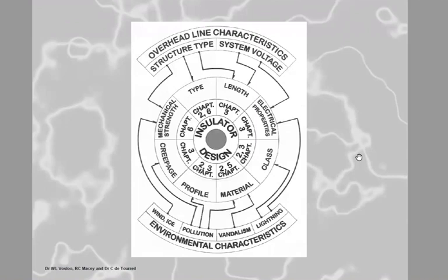You agree? The backbone. And that backbone is most probably the cheapest device when you're building this whole structure or building this line, whether it's in the substation or whether it's on the actual transmission or distribution or MV line. The insulator is actually the smallest costing component in relation to the conductors and the structures and all those things. Now, how do we select this insulator to give you a good life? You don't want to go out there and not be able to sleep at night because it's going to flash over electrically, or even worse, mechanically fail and be a safety hazard to your population.